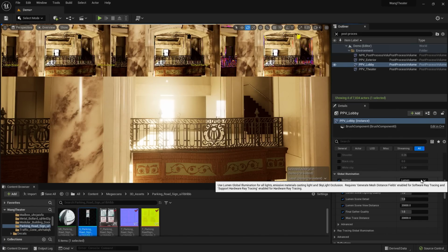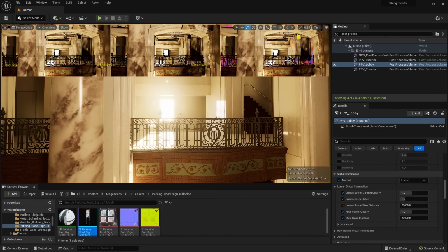So if you're getting pink or yellow, it's visualizing the geometry that has not been culled. So in this case, this geometry may be too small to be considered for that Lumen calculation. So you'll notice that here, the yellow is coming up black within the Lumen scene, meaning that it's not a part of that Lumen calculation.